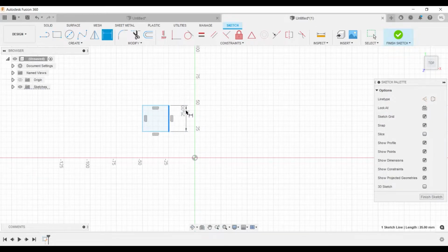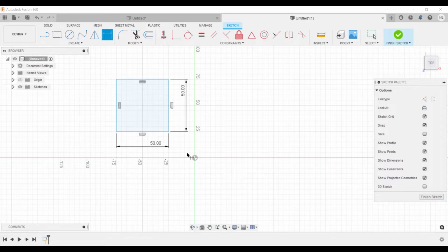First, hit Sketch, Rectangle and add dimensions. Second, press D, the hotkey for dimension, and add a value. It doesn't matter which dimensions you put in for this example. Stay close to the central geometry mark. You will create a reference to that next.